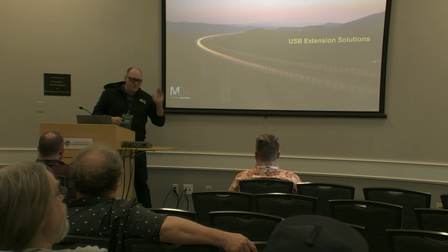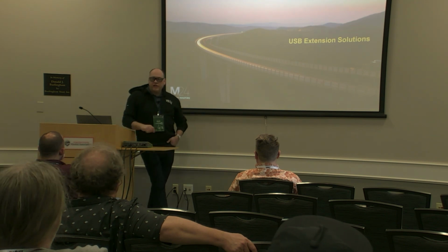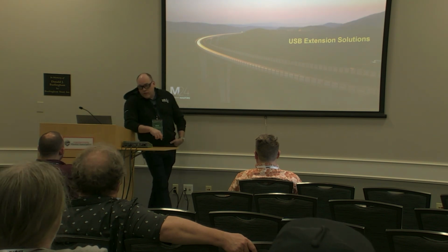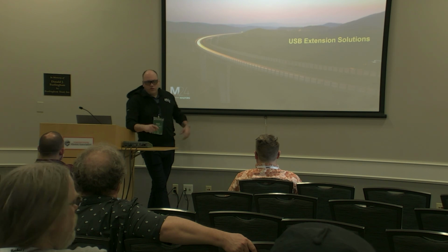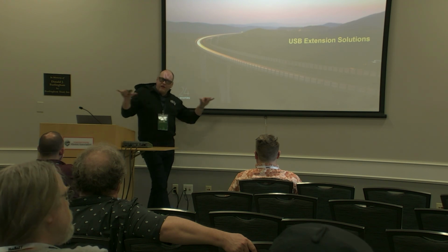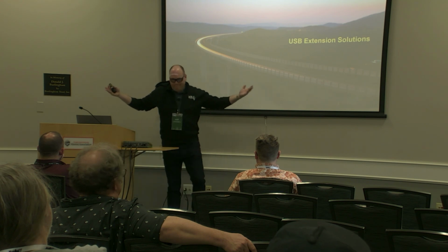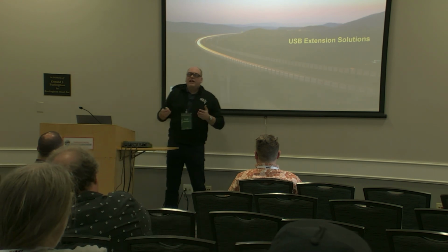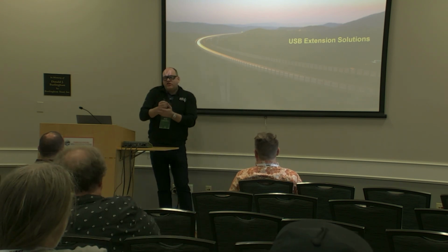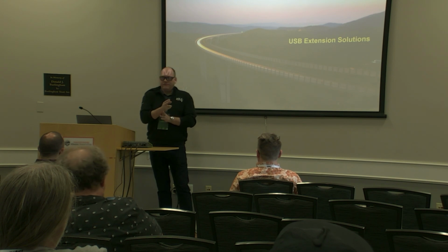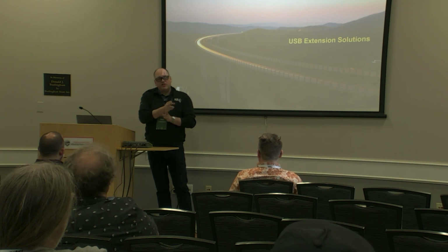I do have a whole bunch more content in here, but that's all more Crestron related stuff. There's a few other things I want to talk about that didn't really fit anywhere. Clocking, anybody ever heard of clocking as it relates to USB? Can you connect two 6-foot USB cables together, or two 15-foot USB cables? What's going to happen? Not going to work, right? But if you were able to reclock it, essentially that would reestablish the communication.